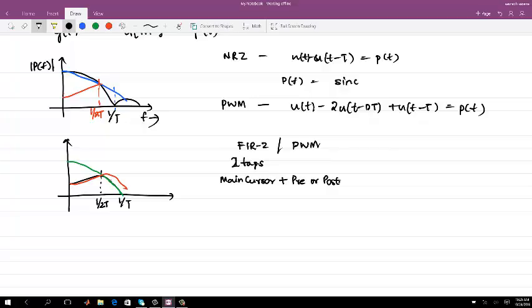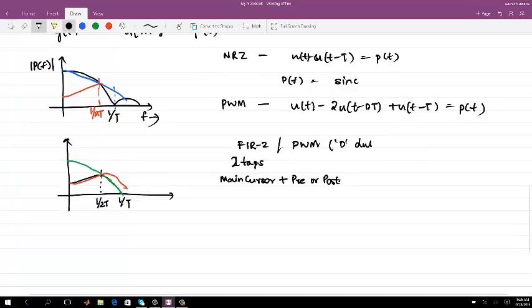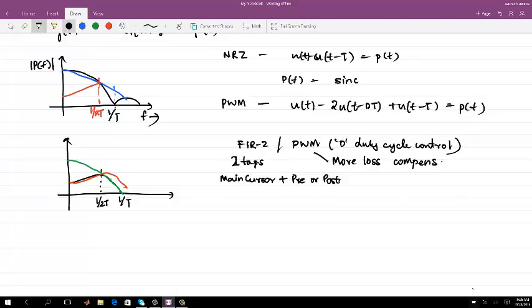So if you compare FIR with PWM, which has only one single duty cycle control, in implementation you will find that PWM can compensate more loss for smooth channels. But this comes with more power penalty because the circuits are now processing higher frequency signal content. Okay.